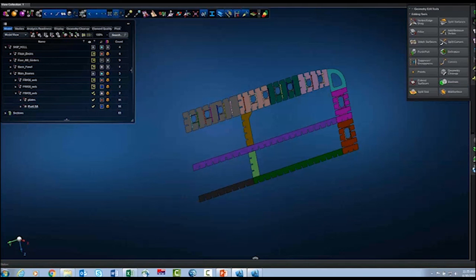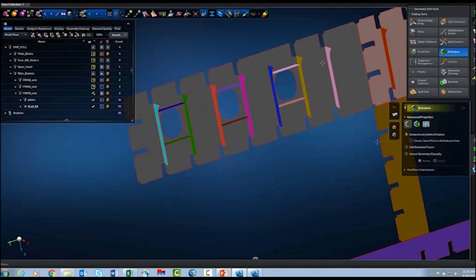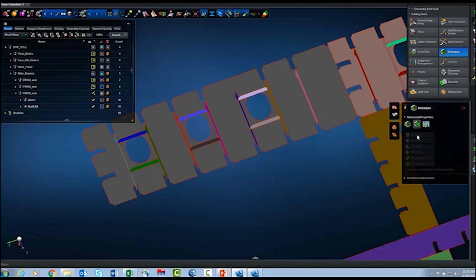The next thing we want to do is get rid of some of the features that are here. Now, you may want to keep those in your model. That's fine. You'll have to use a much finer mesh size, but for my purposes today, I'm going to remove those, and I want to see how to remove them quickly. We've already seen a little bit of defeaturing in Apex. We can definitely do like the onesie-twosie thing, right? And we also have seen that we can go out and find a bunch of features over an individual part or the whole structure, except those features are standard features like fillets and chamfers and